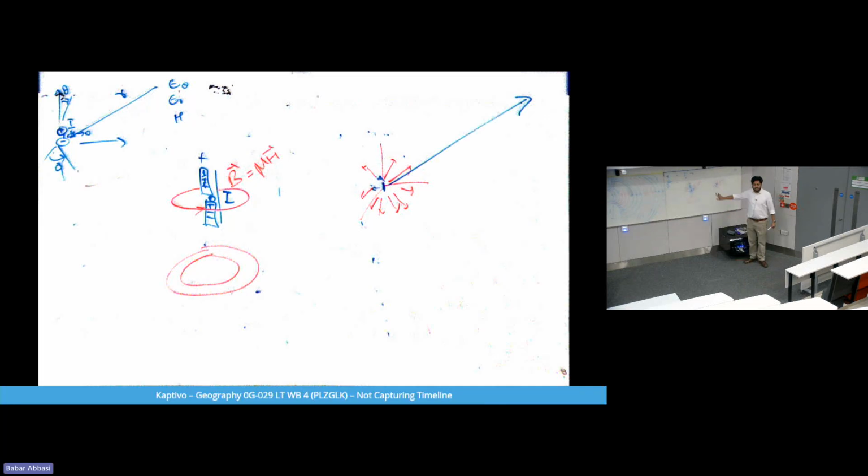This kind of concept is defined by the directivity of an antenna. If an antenna is directive, or its directivity is more, it means it is radiating more in one direction compared to all other directions. For example, if an isotropic antenna has directivity 1, then I need a satellite antenna whose directivity is, say, 20 in one direction and 0.2 in all other directions. It should radiate 20 times more here but very little in other directions, because I'm losing power by throwing it in directions where I don't want it.